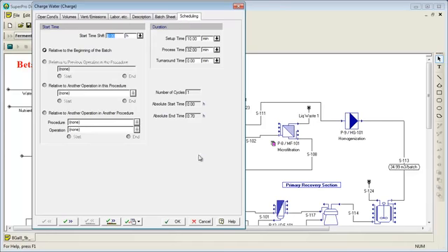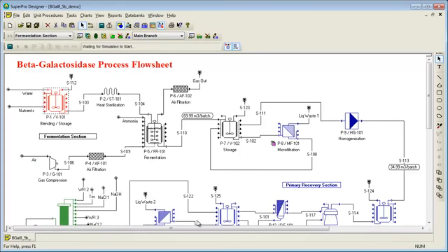In addition to defining unit procedures and operations, the flowsheet connectivity must be established in order to define material flows. This is done by clicking the Connect Mode tool and then attaching input, intermediate, and output streams to the unit procedures. The default stream names can be modified to make them easier to understand. Furthermore, the input stream compositions must be specified based on the materials available within the project.